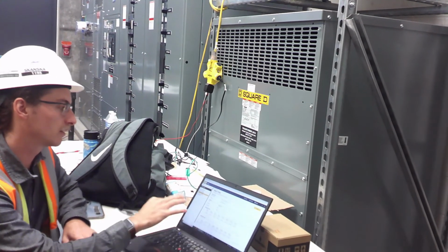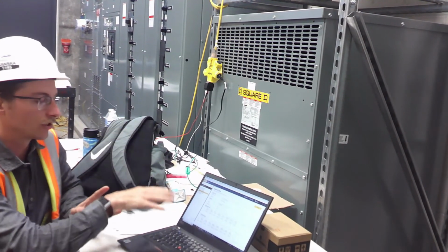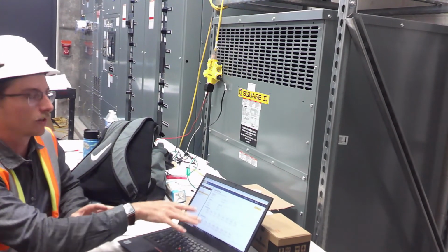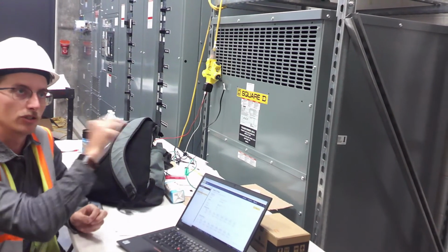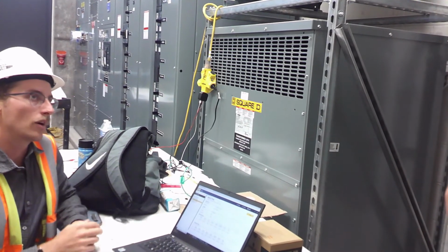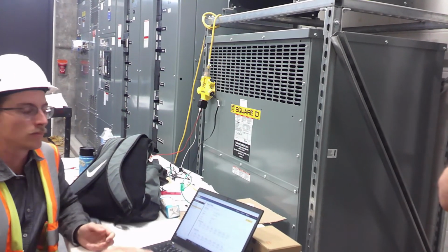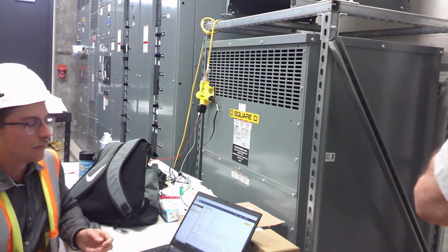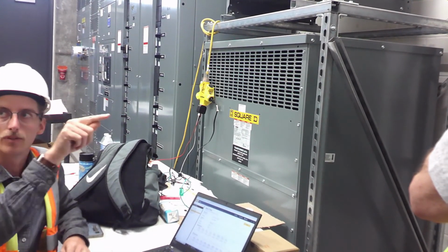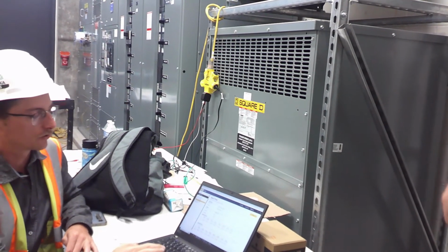What that does is a bunch of the schedules and sensors are referencing your open and close times instead of just having a direct time set in there. So if you wanted all the corridors to kick on at 7 a.m. instead of 6 a.m., you come here and change the time. Instead of having to go through every single individual zone and change it, you can change it all just from this one spot.